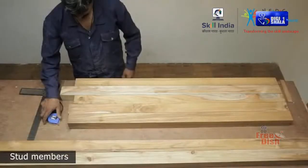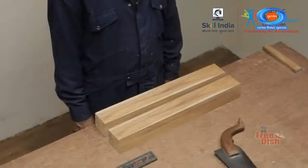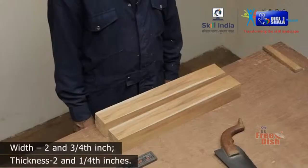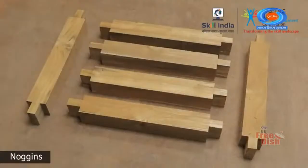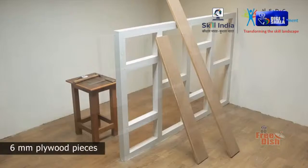These will form the studs of the wall frame. Use 2 wooden pieces of width 2 3/4 inch, thickness 2 1/4 inches. Cut these into 6 pieces to form the noggins. In order to complete the wall, select 2 plywood pieces of 6 mm thickness.